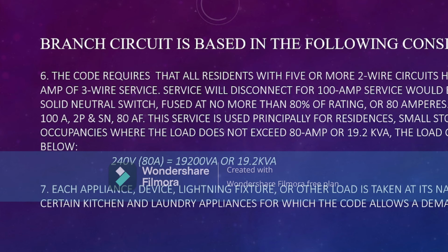This service is used principally for residences, small stores, and other occupancies where the load does not exceed 80 amp or 19.2 kVA. The load calculated is shown below. 240 times 80 is equal to 19,200 VA or 19.2 kVA.